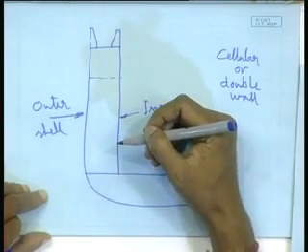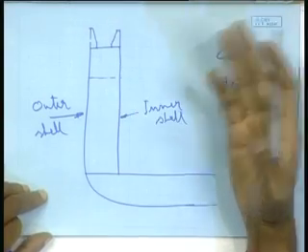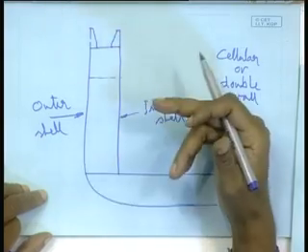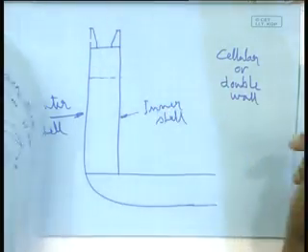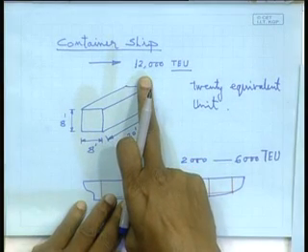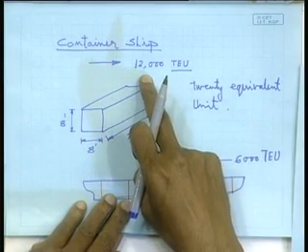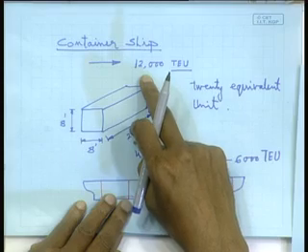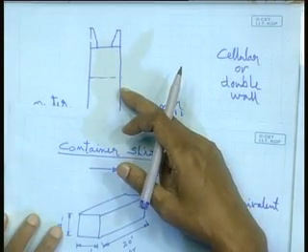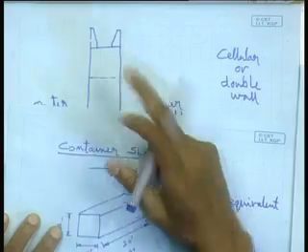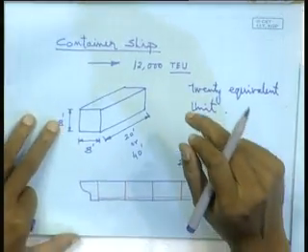So, that calls for double wall construction, obviously. As you are saying, it will not only add to the weight, it will add to cost, isn't it? It is additional work, additional material, it will add to cost. But this has become a necessity as we are growing in size. Probably, if you design a 6000 TEU container ship, you do not go for double wall. It will not be a wise decision. But if you are building a vessel of 11,000 TEU, probably you will have no other option than to go for a double wall.